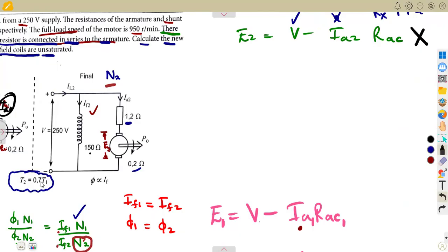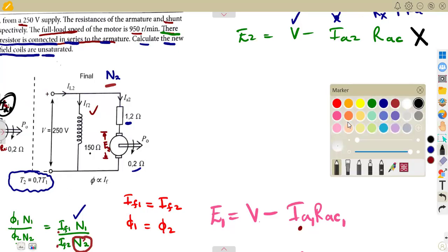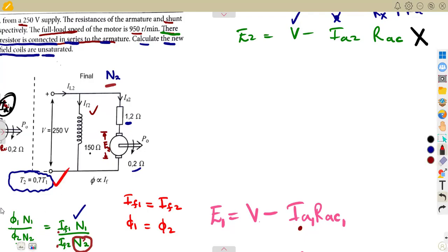So let's think along what we have, because there is a condition here that we are given about the torque. What is it that we can have? Because what we need is the armature current. So from the load current, let's forget about that because there are going to be two unknown values. Just forget about the load current, and think of another way of getting this same armature current. Let's go back to our formulas, because of the torque that we have.